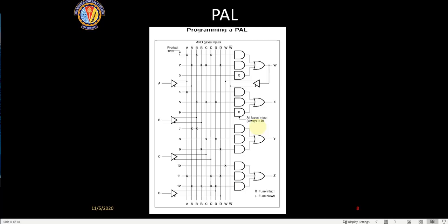Sir, so we could use this to get past the limitation of total number of inputs, as we discussed previously, that if we have a PLA that can take only 3 inputs at a time, we could use this. If we have an expression which has say 8 variables, then we could combine PLAs, split terms accordingly and get the minterms out of each PLA. Yeah, correct. So we can use that aspect. It will be very clear once we see an example.